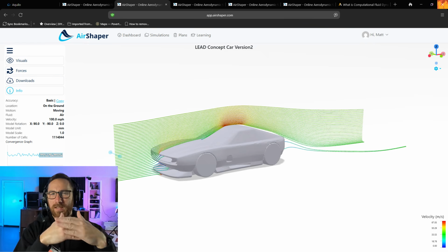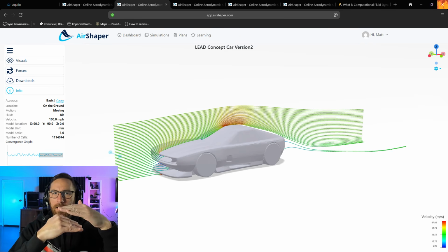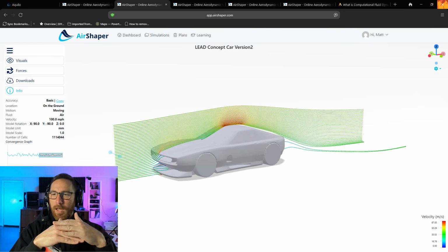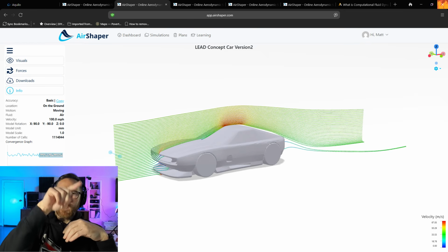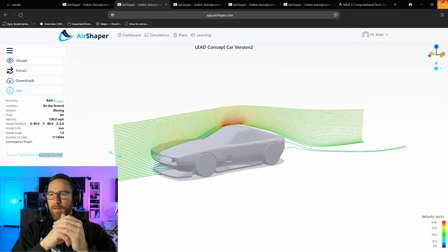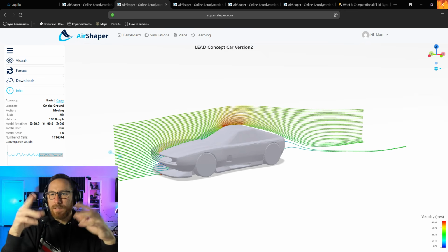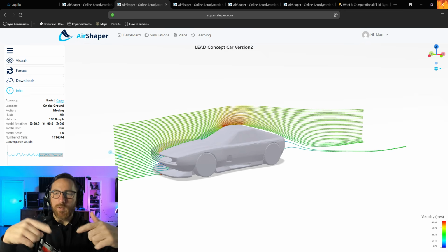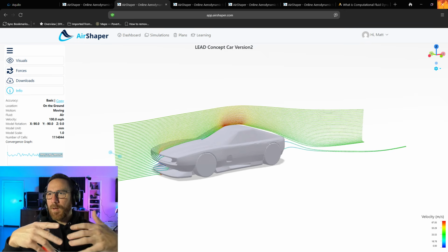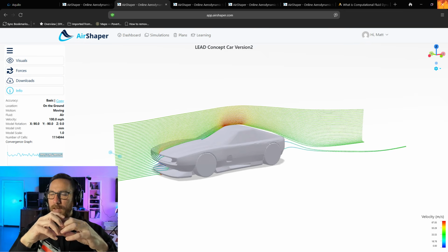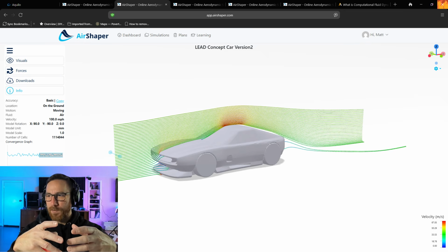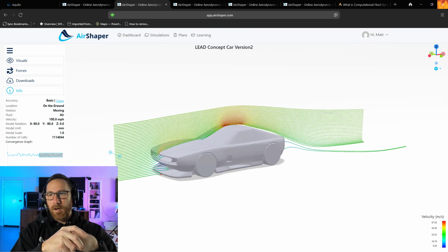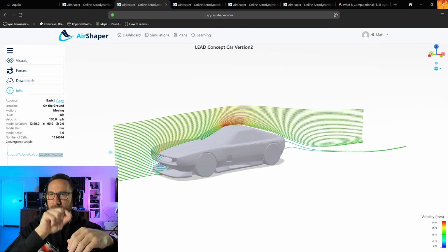normalizes or feels like the results are within a range, basically this error range. And once it feels like they're not going outside of that, above or below, then that's kind of a normalized model. And typically this takes thousands of solves, thousands of times running through this. And when we think about solving and setting up a resolution, like the number of cells that we have, this is going to calculate basically what's happening into and out of each of these cells.